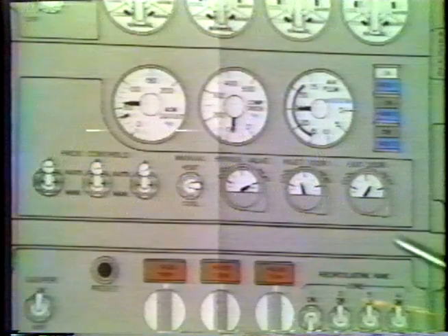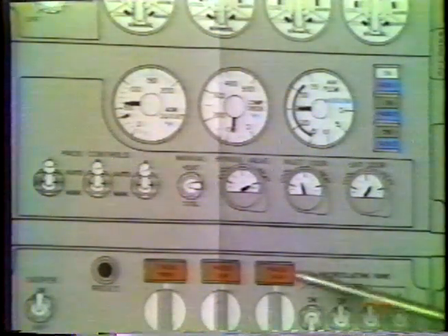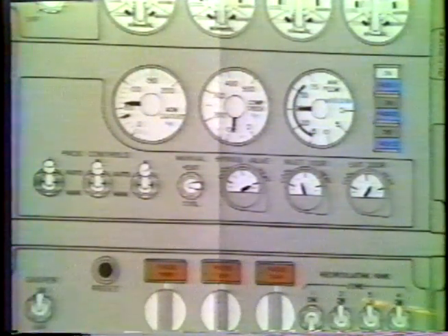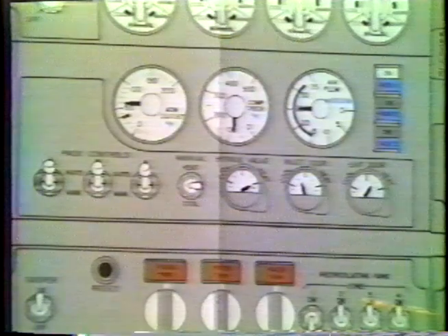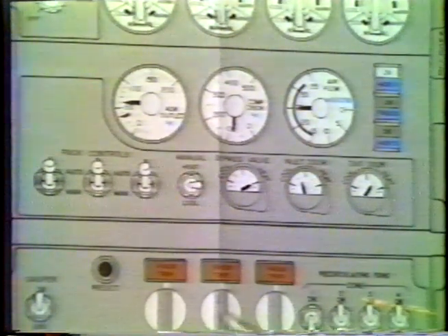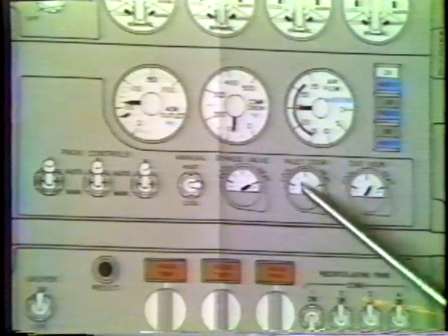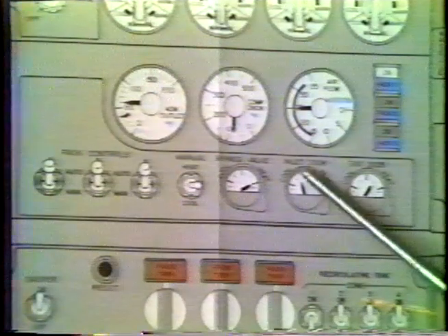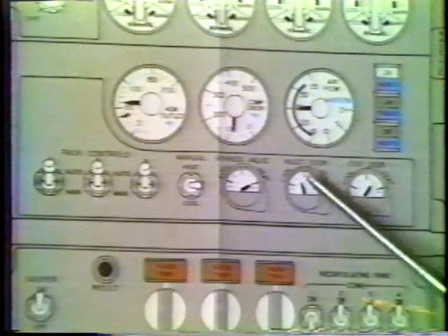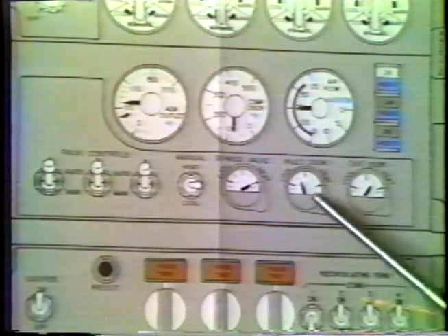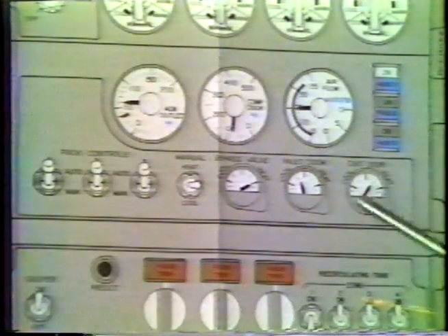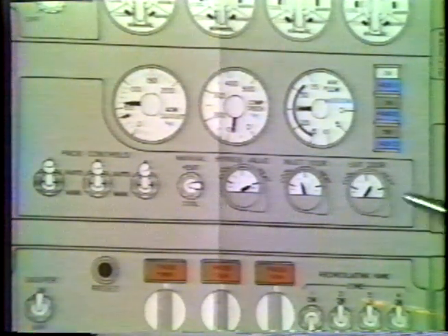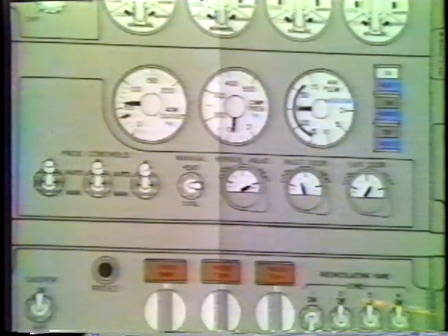In my experience, most pack trips are due to the doors being out of sequence, and they generally occur during initial climb. If you hit the reset, you can get the pack back, because by then the bypass valve is in full heat and the cooling is done by the control of the inlet door. Of course, the troubleshooting procedures in the flight handbook should be adhered to if necessary.